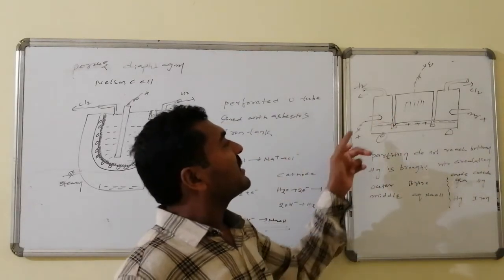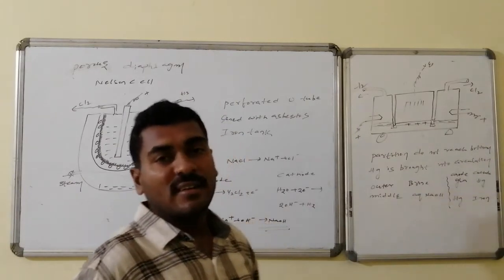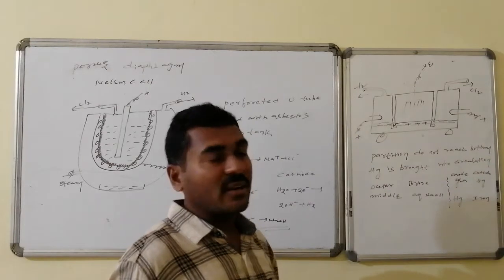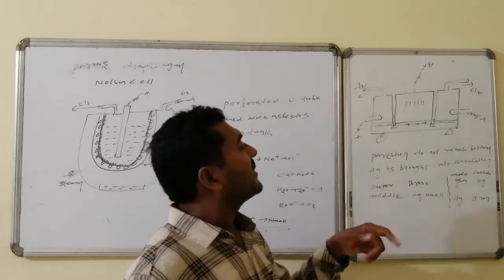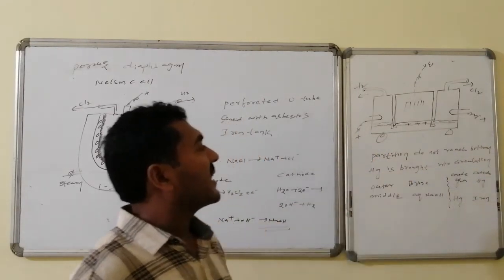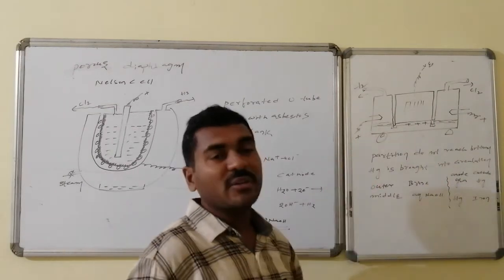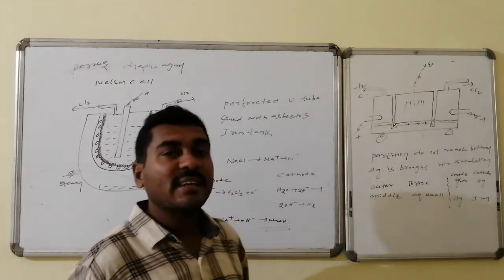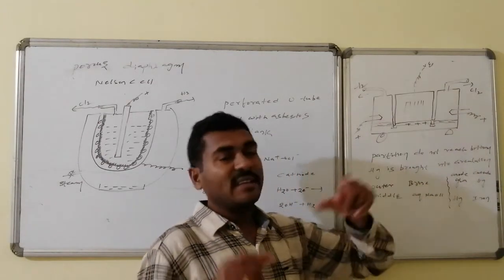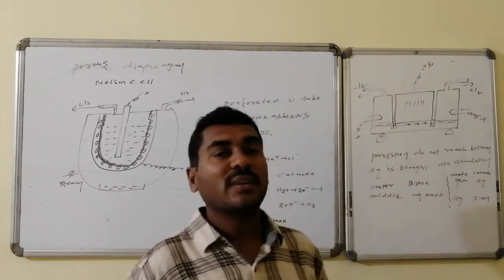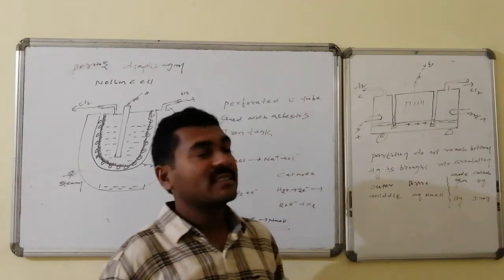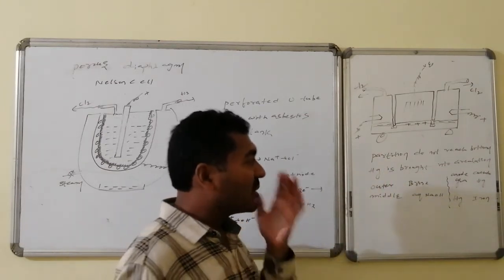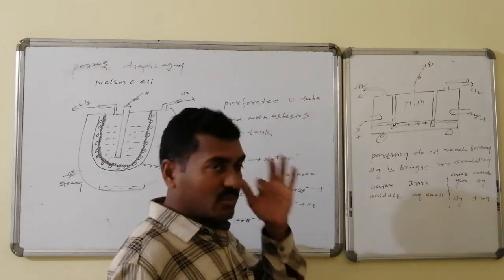The outer compartment has outlets for the generated gas, and here it has graphite rods as anode, and here also the graphite rod is acting as anode. In these outer compartments, mercury is acting as cathode, whereas in the inner compartment the same mercury is acting as anode, along with a set of iron rods. A set of iron rods kept from the top act as cathodes. The partition does not reach the bottom, and mercury is brought into circulation.